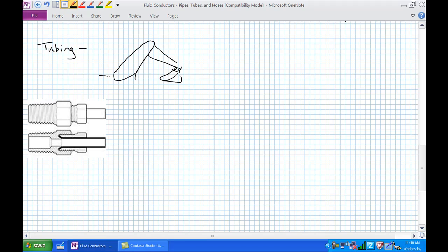Here's the shoulder joint, elbow. So it's going to be a hose here because the shoulder joint is moving, but it's not moving along the length of that boom. So that's where you're going to put tubing. Here's your elbow joint, there's a hose, there's tubing, there's a hose. Basically, tube, tube, but it may require some gentle bends along the length of that boom and or stick. And those hoses at the joints are actually moving.